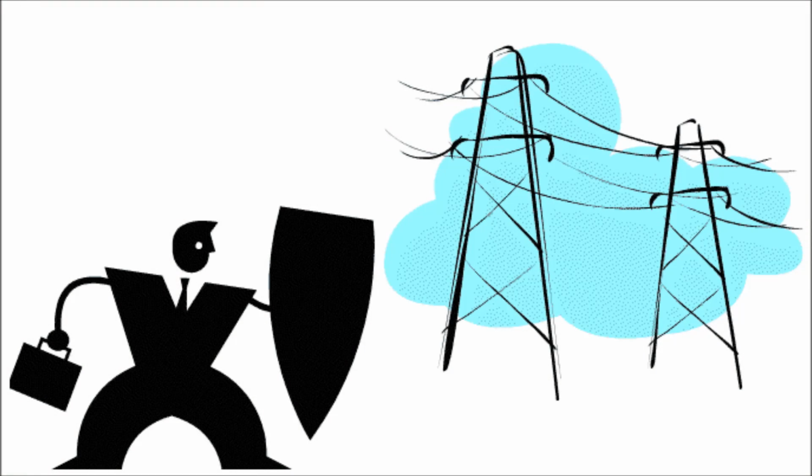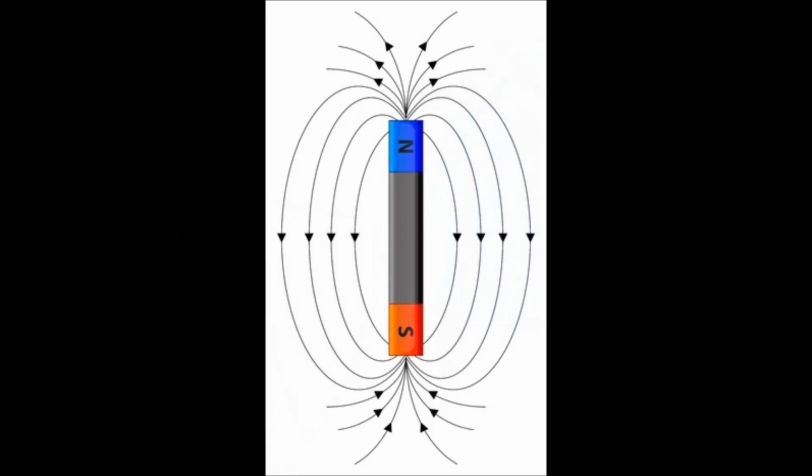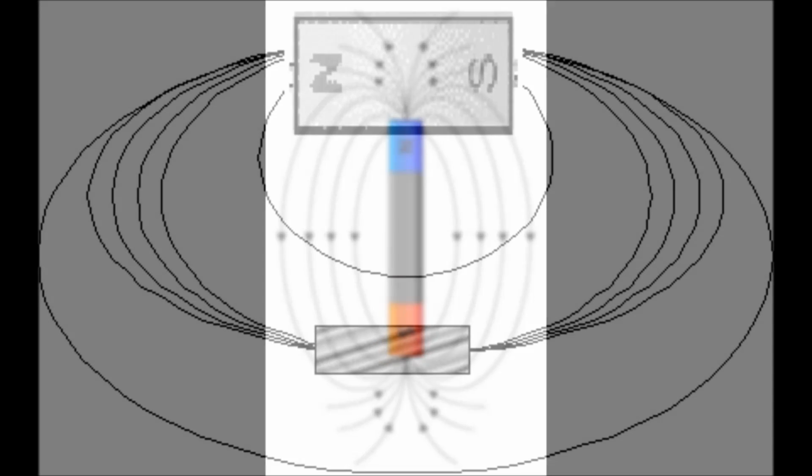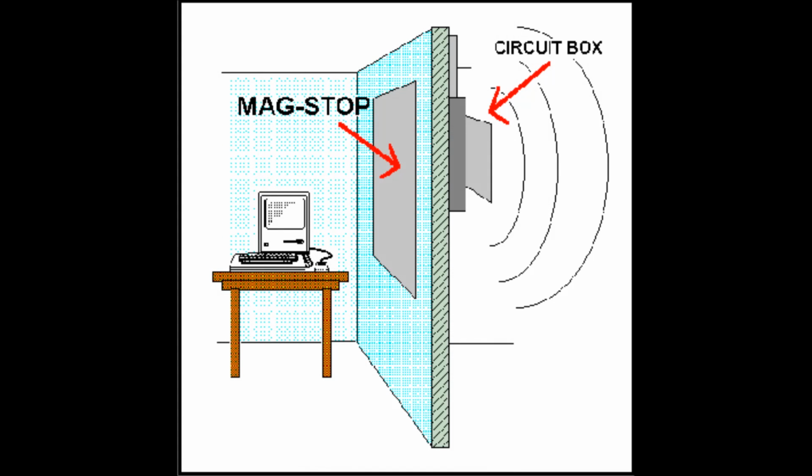Remember, the magnetic shielding is not really shielding in the traditional sense. One cannot stop or block magnetic field lines. They will travel from the North Pole of the source to the South Pole. What we can do is alter the path that these magnetic field lines take on their journey. One could say that magnetic shielding materials conduct magnetic field lines better than air and most other materials. In a sense, they create a path of least resistance in which the magnetic field lines can travel. As a result, there will be less magnetic field in the area around the shield. But the magnetic field lines will only travel in this alternate path if it is a low enough energy path, not because we just want it to.